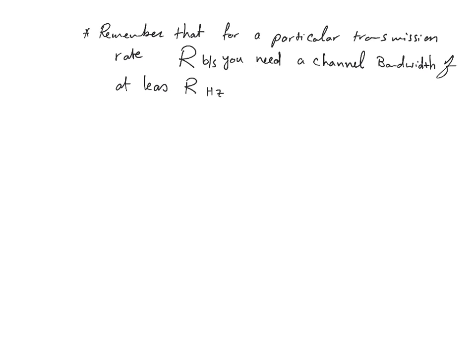Again, you can achieve that by converting bits into symbols, but it becomes the same thing. When we talk about rate, in that case, it's going to be symbols per second. So we are talking about the rate that goes into the channel, not the rate in some intermediate stages of the system. When you use digital modulation, what's going to enter the channel is symbols per second, and the channel has to support at least a bandwidth equal to the number of symbols per second, right?